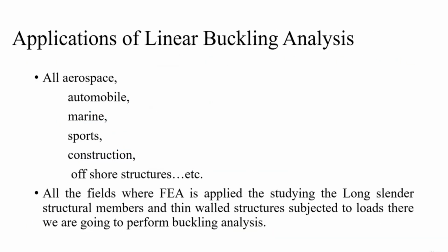Then, applications of linear buckling analysis. As we have seen earlier, it is applied in a lot of areas like aerospace, automobile, marine, sports, construction, offshore structures, etc. In all the fields where FEA is applied for studying long, slender structural members and thin walled structures subjected to compressive loads, we compulsorily perform linear buckling analysis, because we first perform it to understand the behavior and then change the design. Once we are satisfied with the design, we go for nonlinear buckling analysis if required.